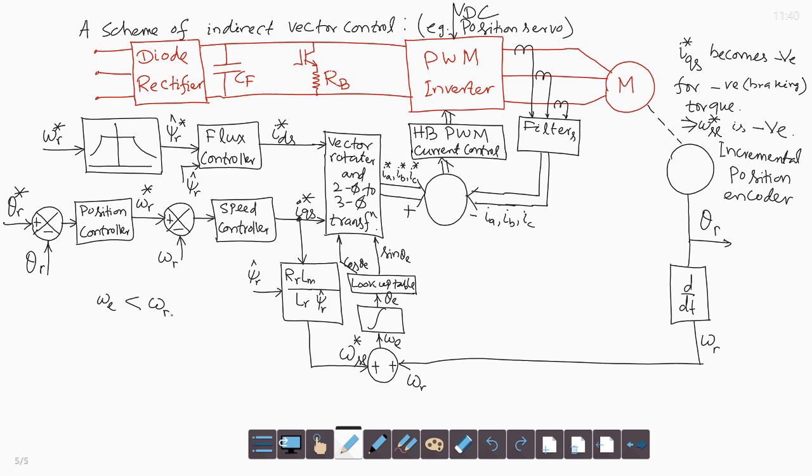When the capacitor charge exceeds a specified upper limit, it should not be overcharged, so by closing the switch S across the DC link, the dynamic braking resistance RB is brought into action. The generated energy is dissipated in RB. This way speed is reduced.